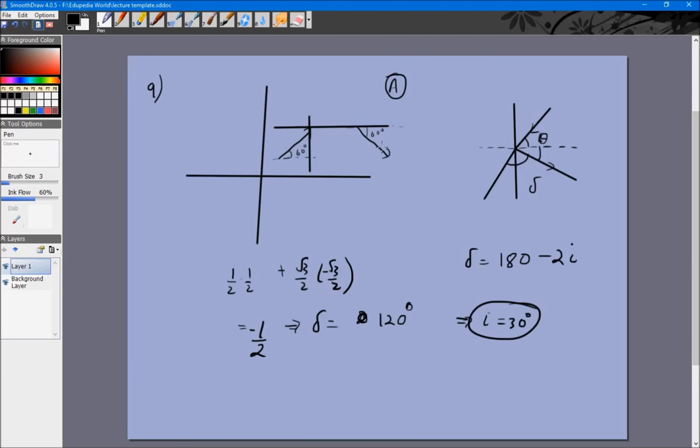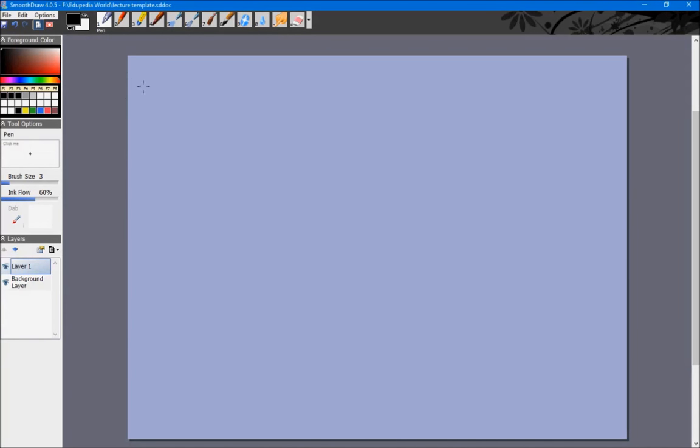The next question, we need to figure out what the actual reading is on a vernier caliper. And again, this is a straightforward application of formulas. First of all, let's calculate the standard parameters of the vernier scale. So one main scale division we can see is 5.15 centimeters minus 5.10 centimeters, or 0.05 centimeters.